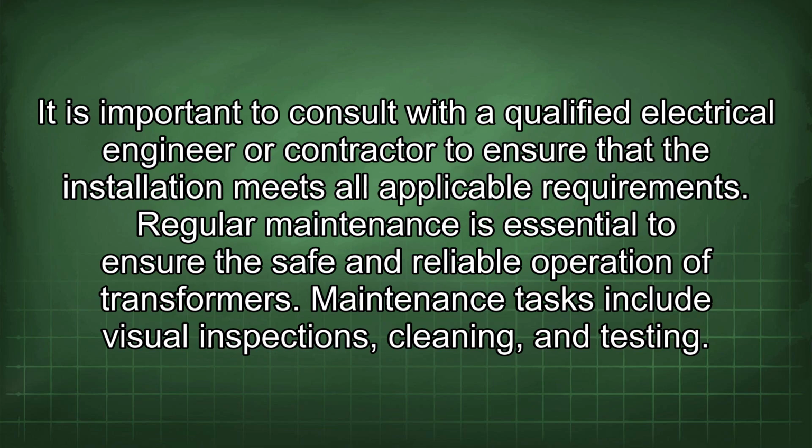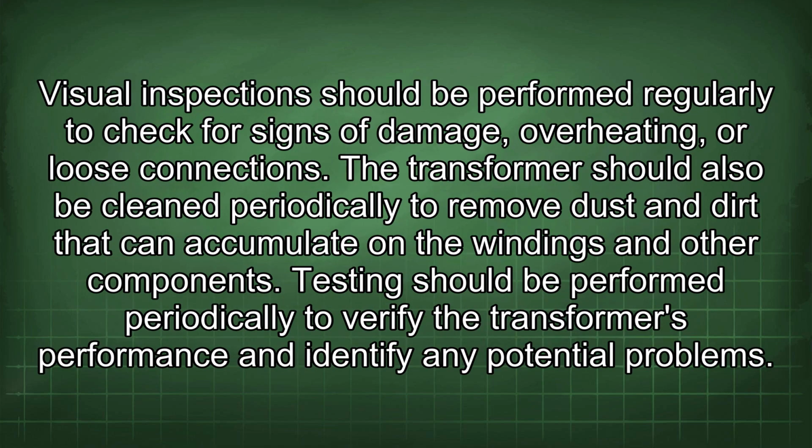Maintenance tasks include visual inspections, cleaning, and testing. Visual inspections should be performed regularly to check for signs of damage, overheating, or loose connections. The transformer should also be cleaned periodically to remove dust and dirt that can accumulate on the windings and other components. Testing should be performed periodically to verify the transformer's performance and identify any potential problems.